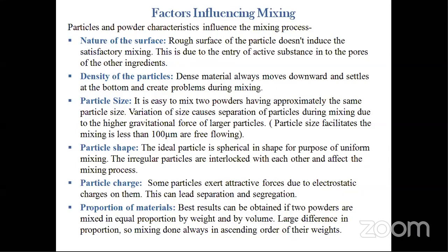Particle charge is created by frictional forces between particles, or when moisture is present in the particles. At that time, electrostatic charge or van der Waals forces are also created. So you should remember that during mixing, depending on the conditions and the situation, you have to maintain the particle charge.